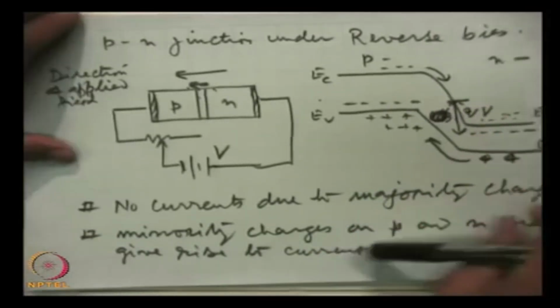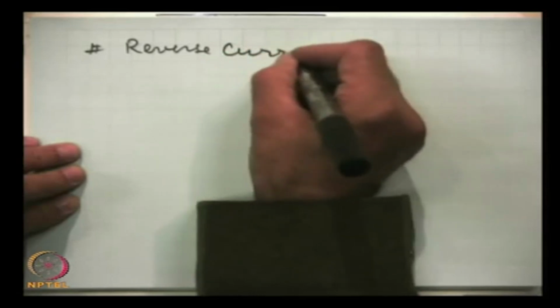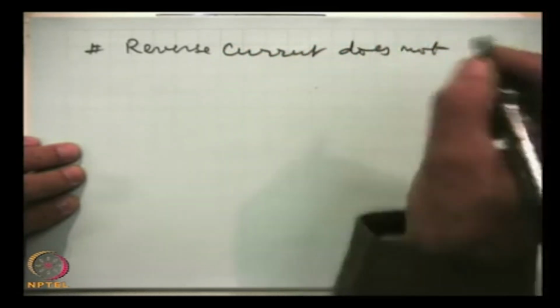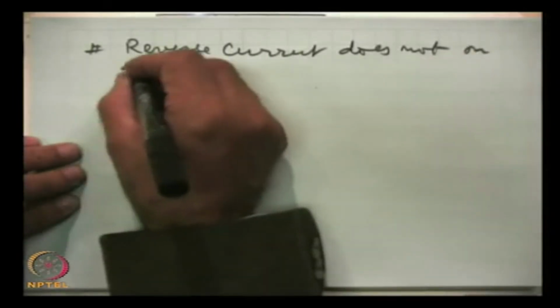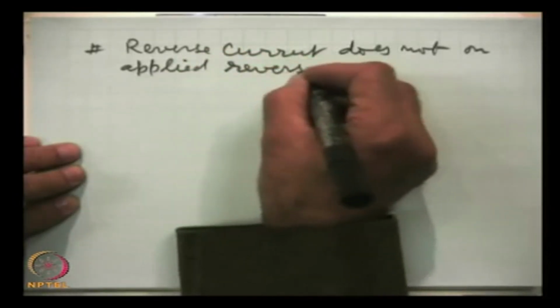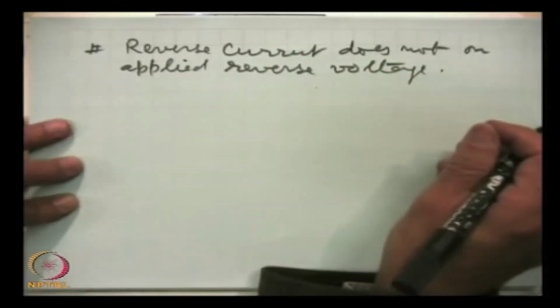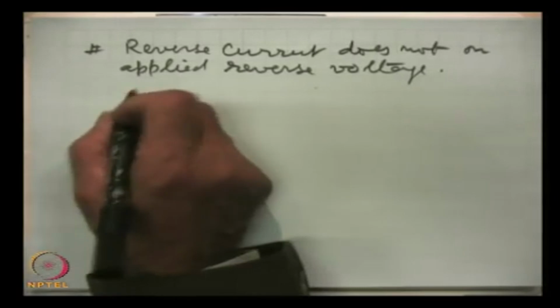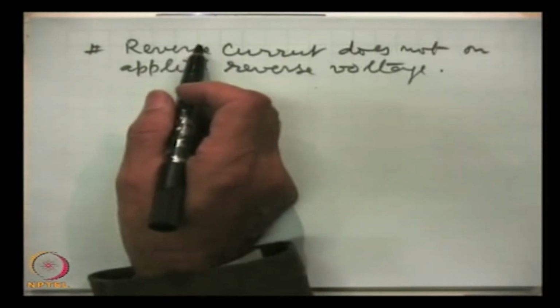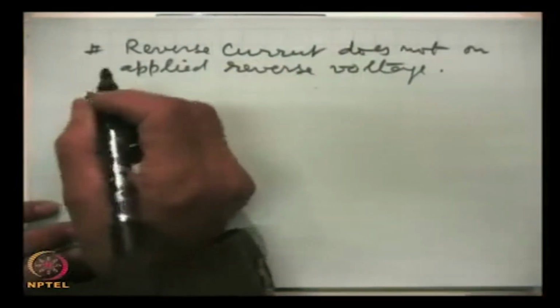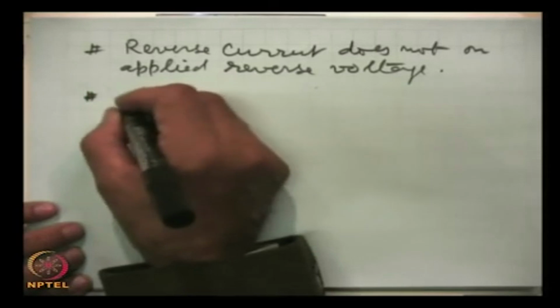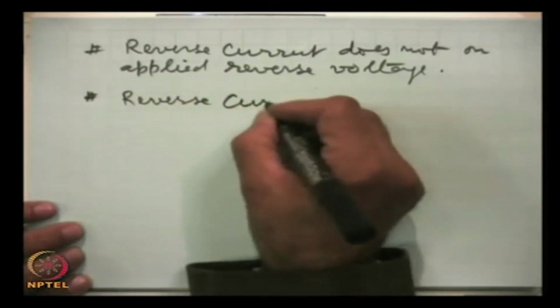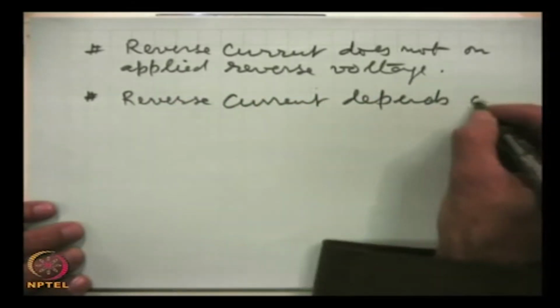Therefore, this is an important point to remember, that reverse current almost does not depend on applied reverse voltage, and because these charge carriers are a function of temperature, reverse saturation current is a function of temperature. Reverse current depends on temperature.